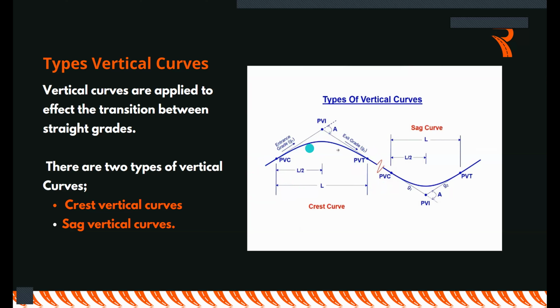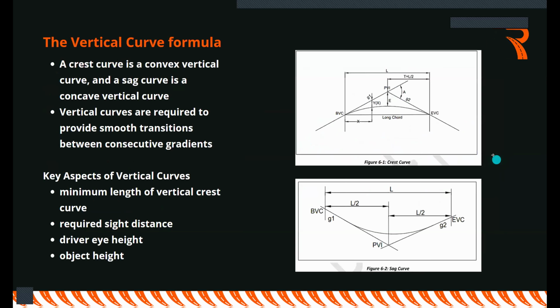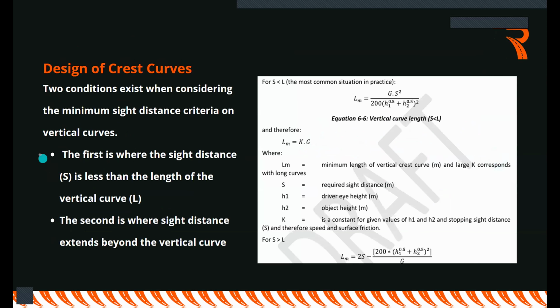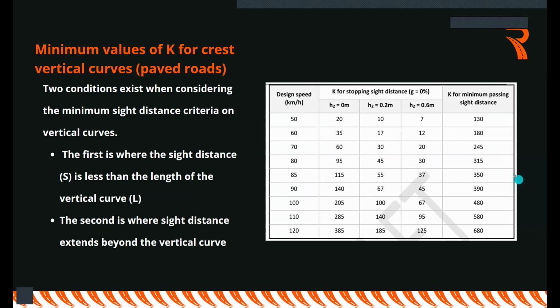The gradient will also be too steep and motorists cannot climb up. Same thing happens here. If this length is too short, this becomes a depression and vehicles cannot transition from this point to the other point. It's basically as simple as that. So those parameters that we are calling K values help us make sure that does not happen.